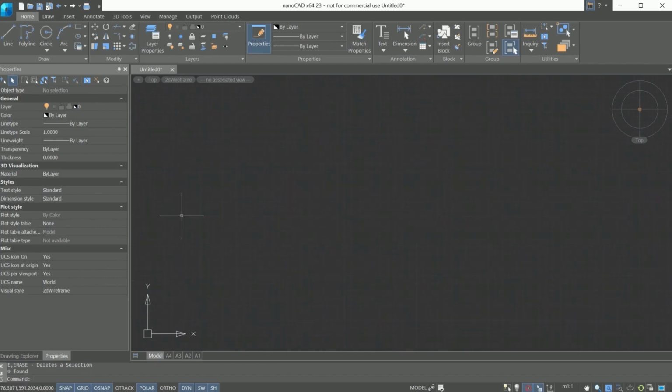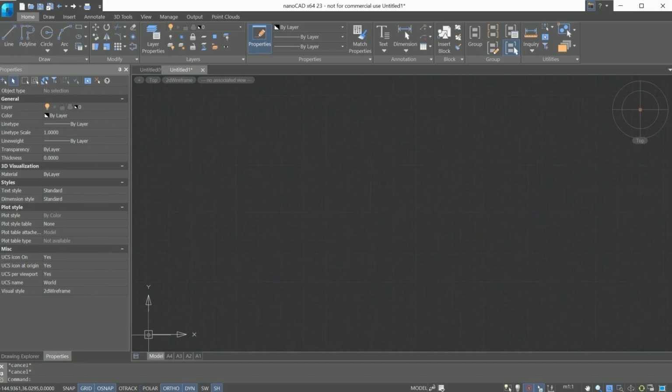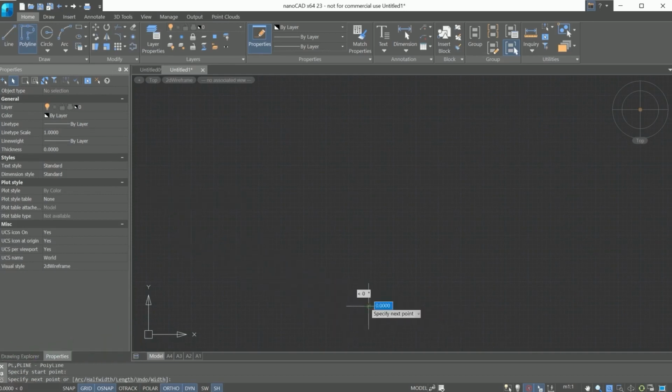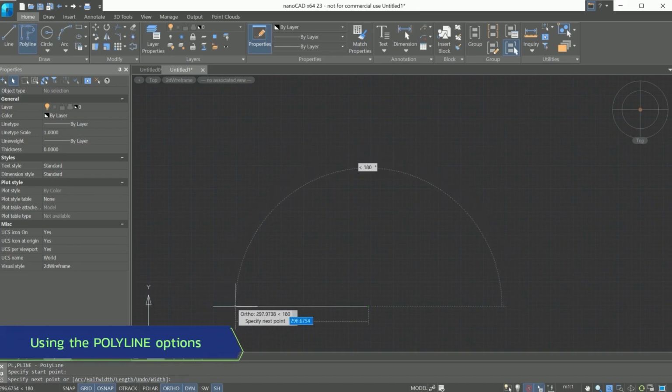We have covered the line. It's one of the main drawing modes, and it's super common in designs. We now know lines can be made individually or in segments, each with its own editing grips to pull, stretch, or move. Next one is polyline. Let's point to a spot in the drawing area and watch the status bar. Polyline can have both straight and curved segments, and they all count as a single element.